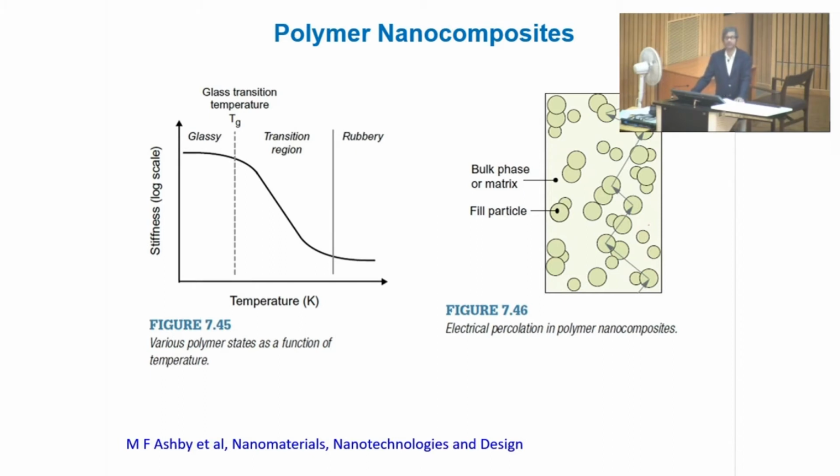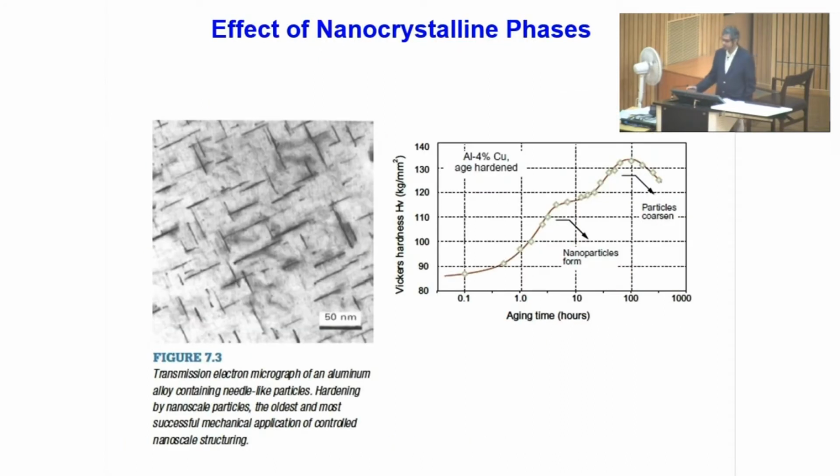So a major limitation of polymer nanocomposites is the temperature issue. You cannot use them at high temperature compared to ceramic and metallic nanocomposites. That is one of the major limitations. In addition to that, due to the nanoparticles present in the second phase, the interface to volume ratio is significantly higher than in conventional composites. As a result, the volume fraction of the second phase can be reduced without degradation of the desired properties. Polymer-matrix composite systems can obviously be of different types: thermoplastic, thermoset, or elastomer. So let me talk a little bit about that.